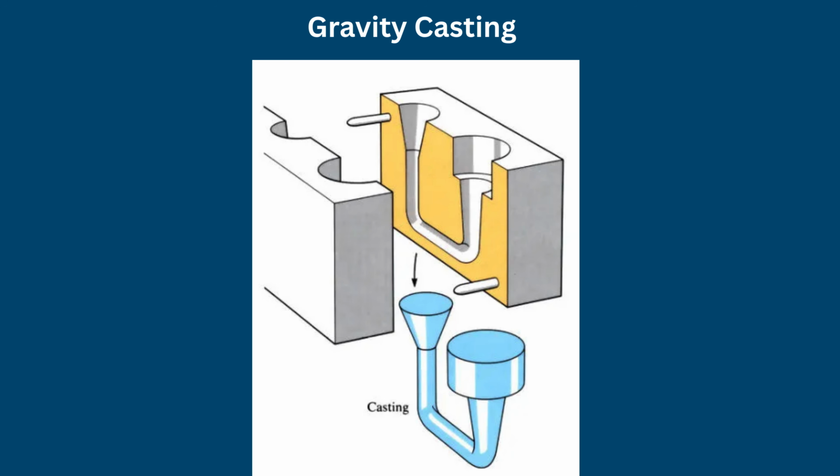Gravity casting. Gravity casting represents the simplest molding method, in which resin is poured directly into an open silicone mold under atmospheric conditions. Although inexpensive, the absence of vacuum increases the likelihood of trapped air bubbles and limits achievable surface quality. The method is primarily used for decorative products, educational demonstrations, and hobby applications.